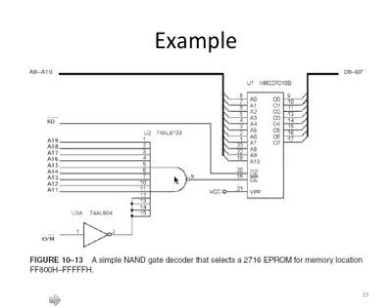Okay, we are using a NAND gate here to perform this decoding, although in the next few slides we're going to talk about a different way of doing the decoding. Nevertheless, in this example, we use this control signal going through a NOT gate, the inverter, and then connect that output to 3 inputs of this NAND gate.